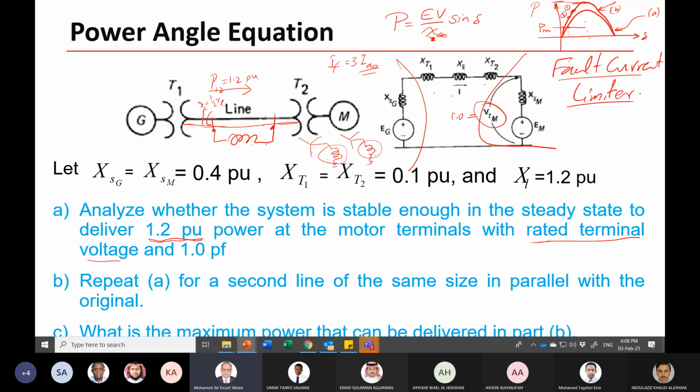So this is, of course, more economic, but there are a lot of challenges here also, in terms of dynamics, in terms of the phenomenon which we call subsynchronous resonance. Introducing this capacitor might excite resonance, and if this happens, subsynchronous resonance will damage the rotor of the synchronous generator. And it happens in real life.